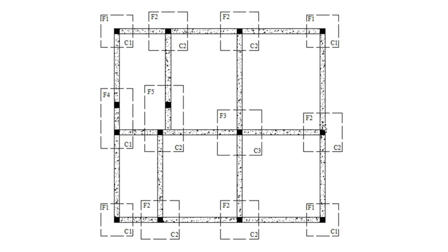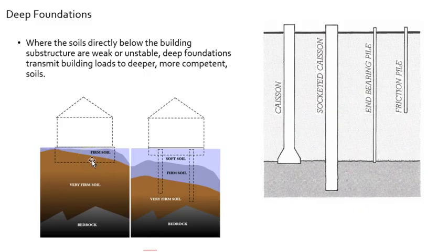And again, one more of the same really. It's just a little different here. We see two columns here, and then just for economy, ease of formwork, ease of pouring, just turn this into one large footing. So there would be specifications elsewhere telling us about F1, footing 1, and then here F2 and F2. So there'd be more detail, obviously, somewhere else telling us how footing F1 is created, footing F2 is created, footing F3. So we have 5 different footing types here, and details further down the line would tell us more about them.